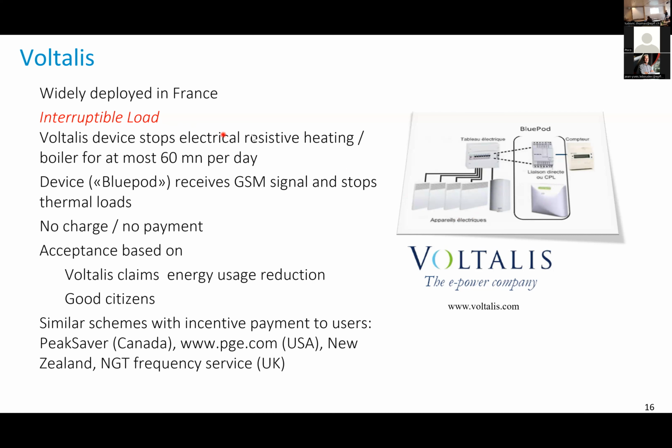The idea of Voltalis is to send a signal to these blue pods that will switch off your resistive heating system and your boiler whenever it receives this signal. They guarantee that it would happen at most 60 minutes a day. Now imagine you're the company Voltalis. They've deployed millions of those devices. Now they can go to RTE. RTE is the French equivalent of Swissgrid.